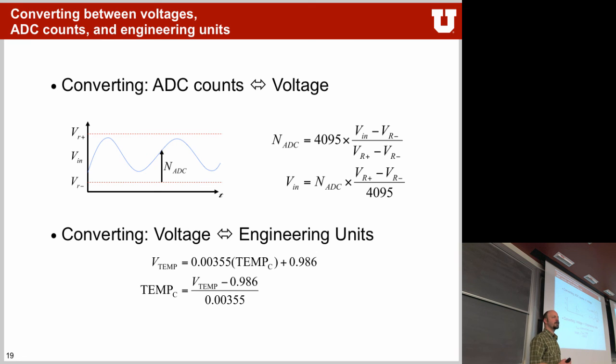Did it all make sense with the reference voltages, what they mean, how to use them? More or less? So why do we need reference voltages? Why don't we always take ground and VCC for your ADCs? Why would you ever want to use something else? Not all sensors run at VCC, yes. And sometimes you're interested in a signal that's much smaller than between ground and VCC, right? What you then can do is scale down the range of your ADCs and get a higher resolution within that smaller voltage.